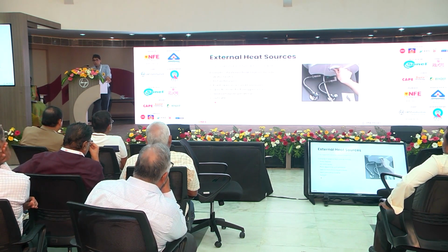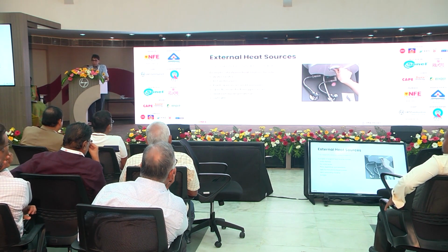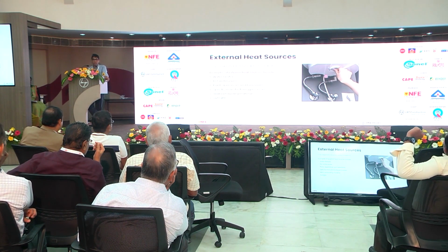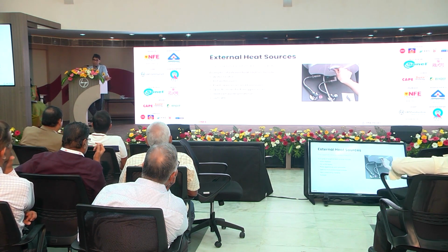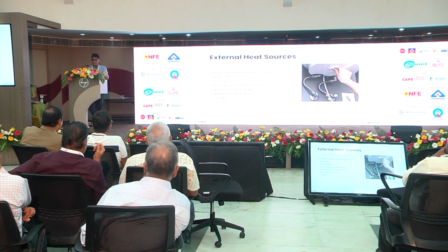Then, some of these could be in our own homes. Like, how many of y'all have seen a geyser installed in a bathroom like this? I'm sure a lot of us, right? So the cable going through near the hot water pipe is going to get hot. And that cable is a flexible cable. It could even be rated for 60 degrees. So, let's say the cable, hot water, let's say 40 degrees, you're only allowing a 20-degree temperature rise. And most of the time, 40 degrees is the temperature we bathe at.